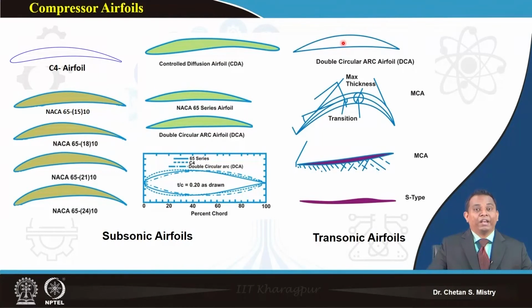In the last session we discussed the limitation of high rotational speed and higher axial velocity. The flow goes transonic, and that increases the losses because of shock formation, which reduces the efficiency. When you go for a more aggressive way of designing to meet future requirements, you need to do your R&D, and that's how people came up with different kinds of aerofoils.